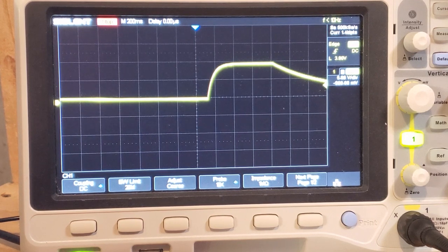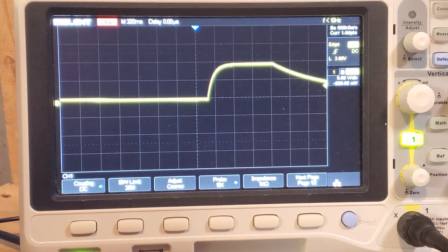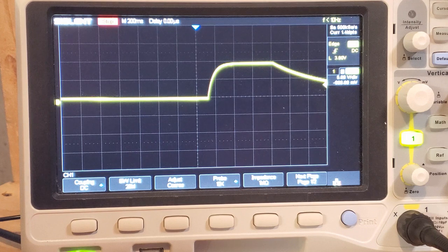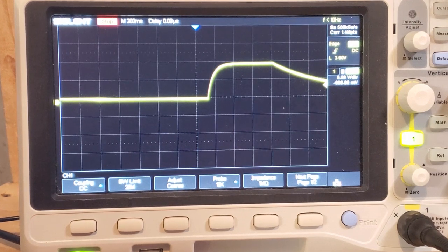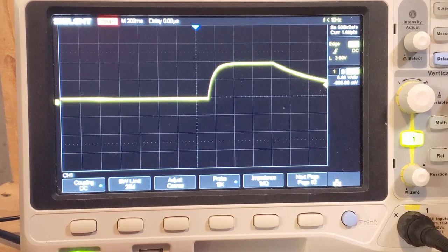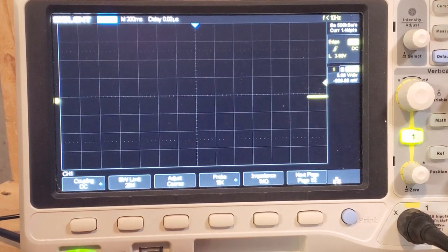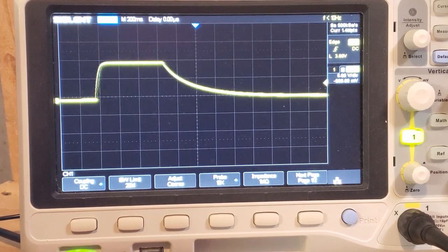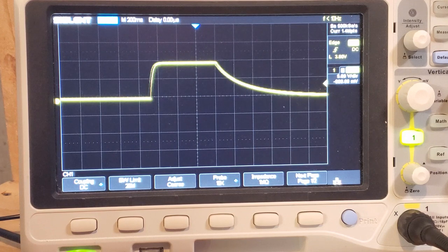Unfortunately, it's difficult to control on the output side because the 680K resistor has to be balanced with the 680K resistance on the output side. But what I'll do is change that 1 microfarad capacitor to a 470 nanofarad capacitor, and you should see the decay will be a lot more abrupt. So let me get on and do that. Okay, so I've replaced that 1 microfarad cap with a 470 nanofarad cap, and there you can see the decay now is a lot sharper.